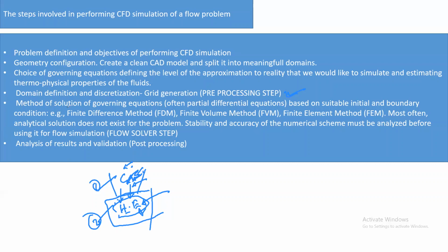Then you can move to the method of solution and governing equations, like partial differential equations, and decide whether you will use the finite difference method, finite volume method, or finite element method, which one will give you the correct result. You have to choose that one. Most of the current commercial software uses the finite volume method. So in our entire course, we will be focusing mostly on the finite volume method, and in the MATLAB course, we will be focusing on the finite difference method.